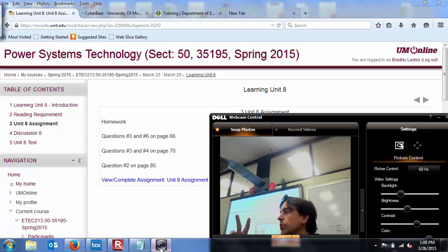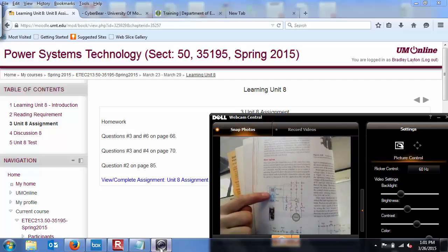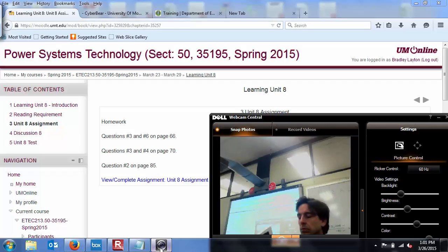Two things have to happen. So it's a little bit like a logic circuit. You have to be holding the button in so gas is flowing, and the temperature sensor in there has to be hot enough to know that the pilot's actually on. If both of those two logic things aren't happening, the gas stops flowing, resulting in a safer situation. And mechanically, it's not shown in this book, but right in here, there's going to be a little spring holding that thing open. All right, so that's question 3.